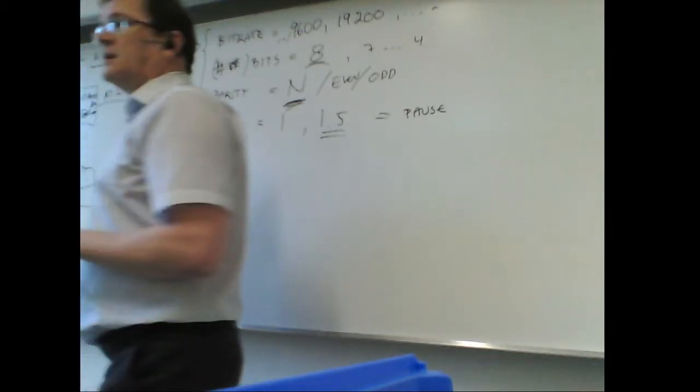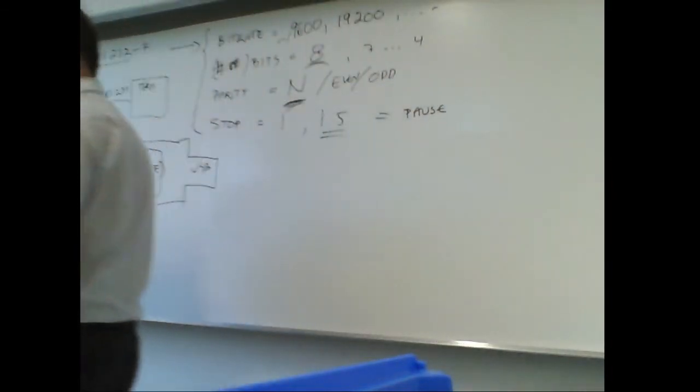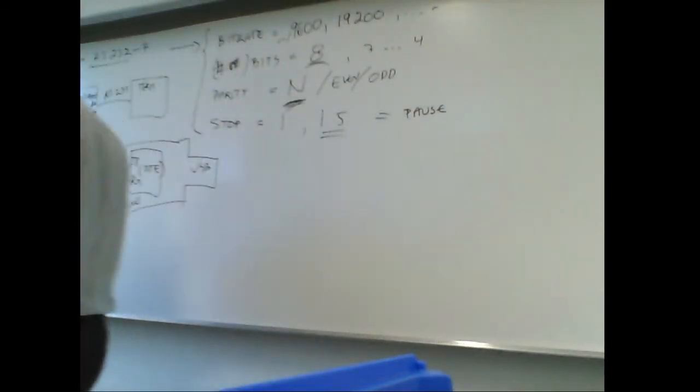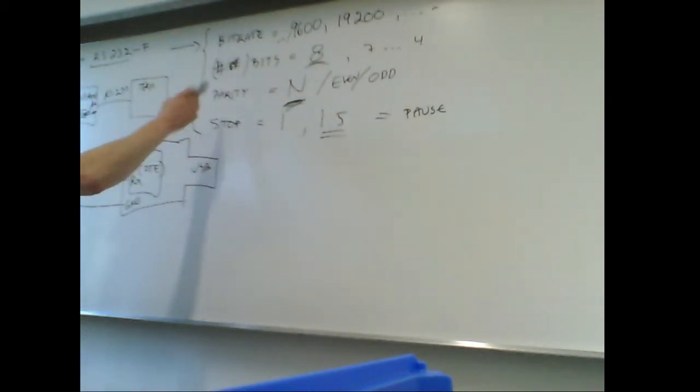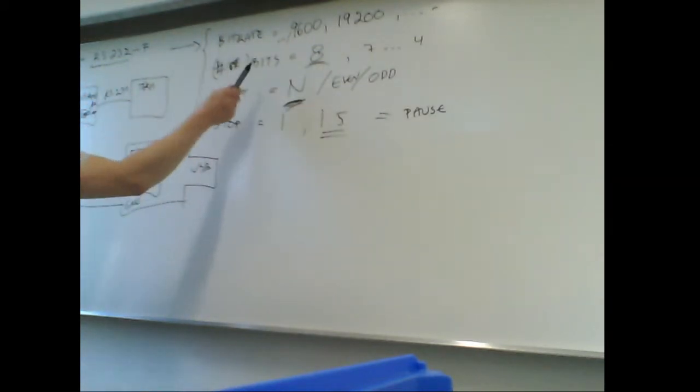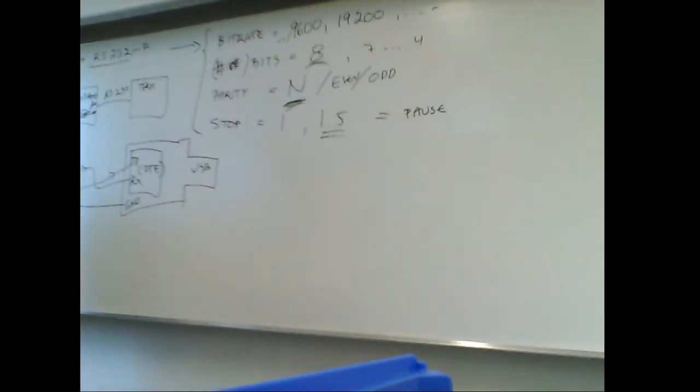And then you have data transmission lines ready. You just need to fix the communication parameters, bit rate, bits, parity, so that they match.